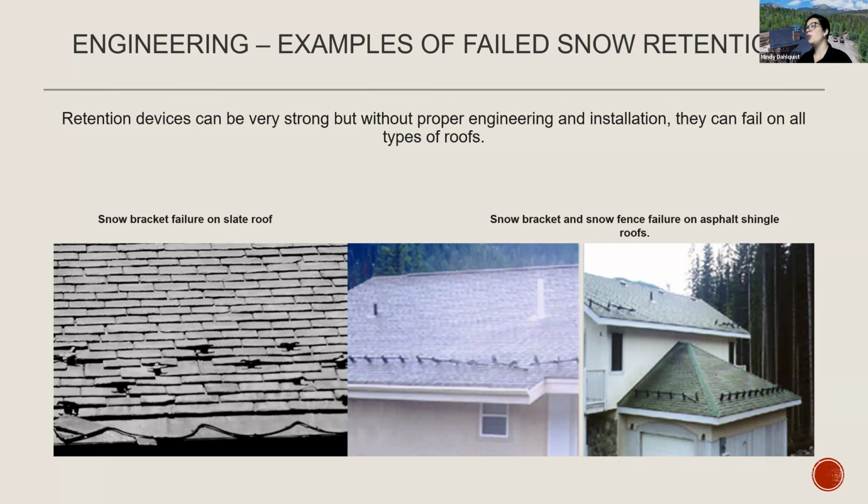And the far right photo, this is one that really points out that upper roof shedding to lower roofs and how that can become an issue. So they decided to only cover the far sides of that upper roof, allowing that accumulated and glaciated snow to end up taking over, folding those fences over on each side and then coming into contact with that lower row of fence, which also took a portion of it out as well. You can really see in that photo where those forces were pushing and where it took those fences out.